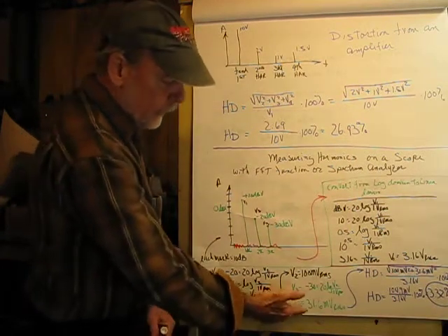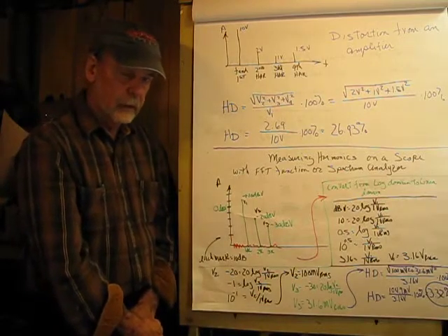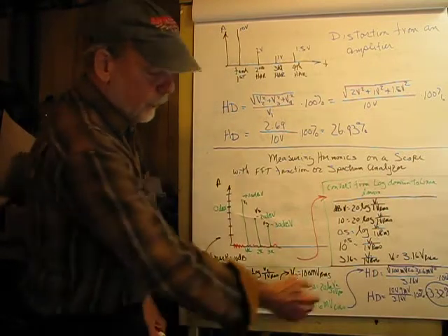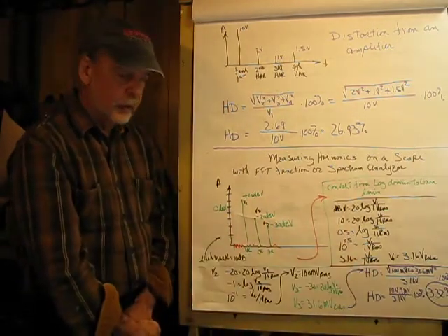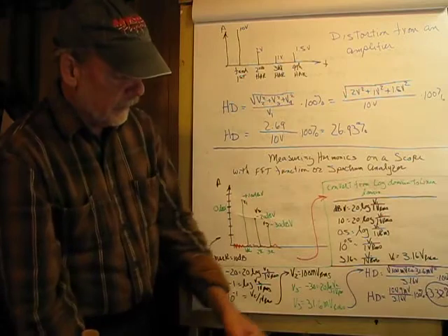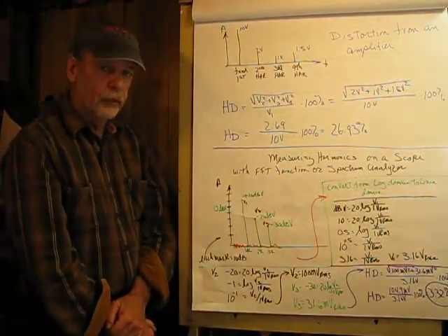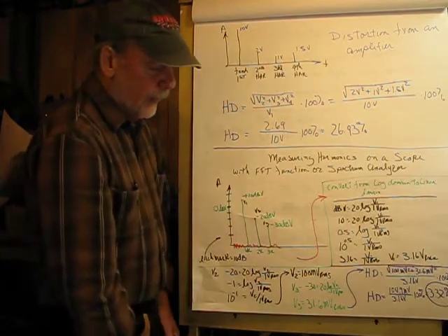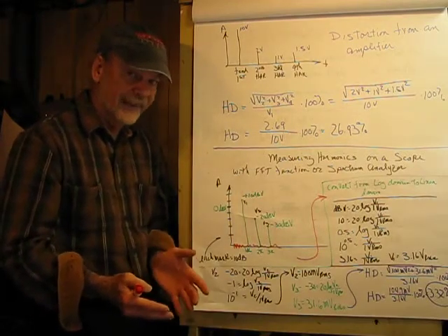Likewise, V3 gives us 31.6 millivolts RMS. So then, if we take and insert that into our harmonic distortion equation, what we see coming out of this is 3.32%. So that would be considered high for a stereo amplifier today.